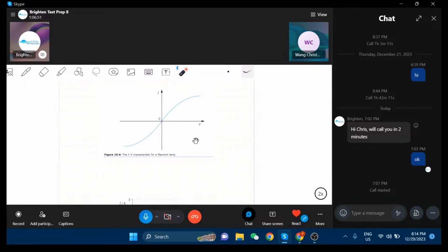Very good, yeah. So we go a bit into differential, right? Here we have the linear behavior, maybe up until here, same thing on the other side. But here we start to have a curve. So that means the gradient starts to flatten out, which means the resistance is going up and up. Exactly. And why would we think the resistance is going up? Because that is maybe counterintuitive, right?